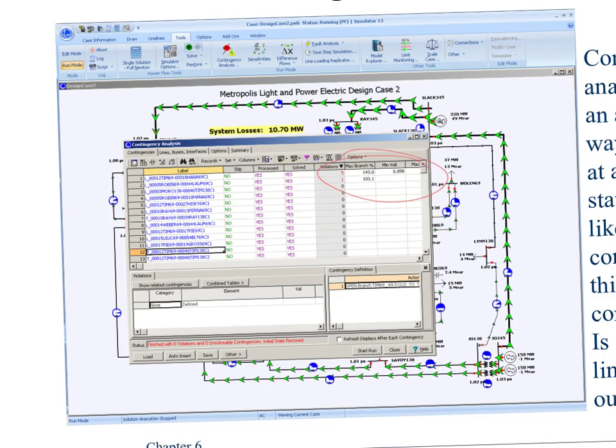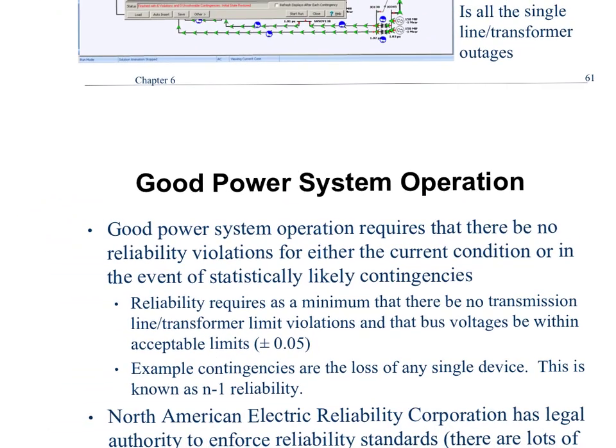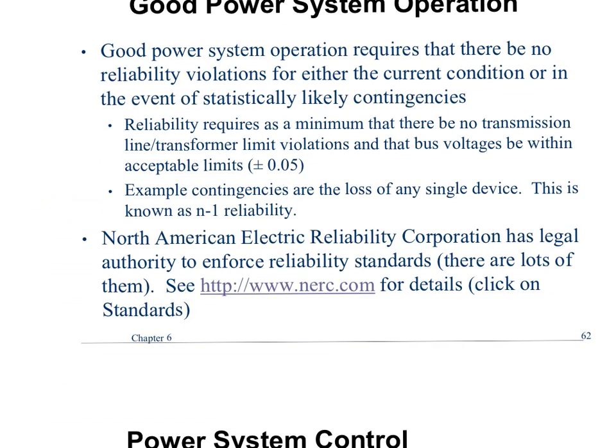So that's contingency analysis. We'll do this fairly quickly. I talked most about it, right? So we have n-1 contingency, and we want our voltages to usually be within plus or minus 5%, no line or transformer. Notice we don't talk about frequency. Frequency limits are much tighter. If the frequency on the grid varies more than like 0.01 hertz, that's a big deal.